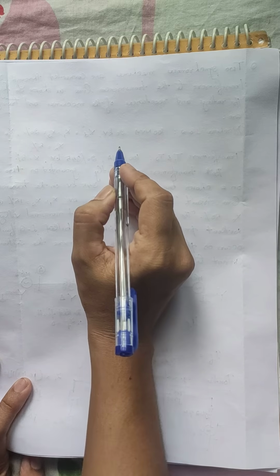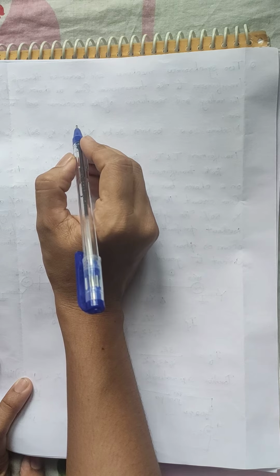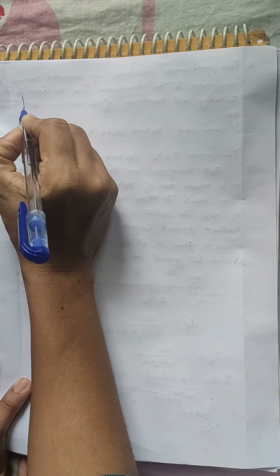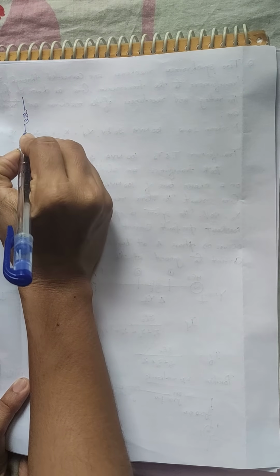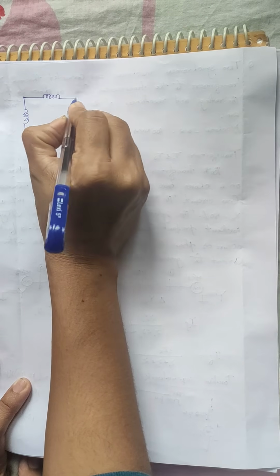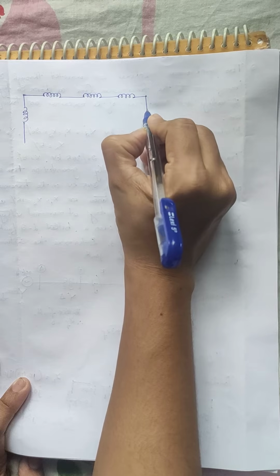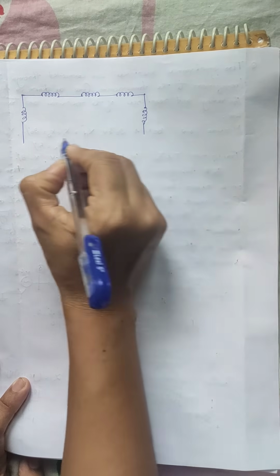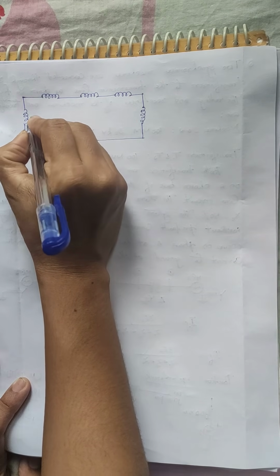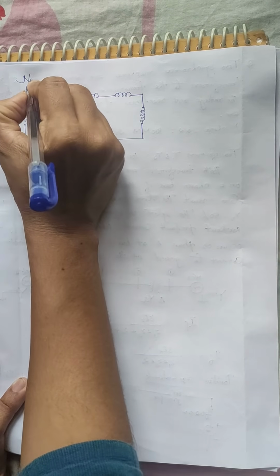Now we have to calculate the total negative sequence reactance Z2. For that we have to draw the negative sequence network for the complete power system network. So in the negative sequence network, the machine 1 will have the negative sequence reactance only. There is no voltage source. Transformer T1 has a series reactance, transmission line has a series reactance, and transformer T2 has a series reactance, and machine 2 will also have a series reactance only. So the values are J 0.2 for the machine 1 negative sequence. This is the negative sequence network.